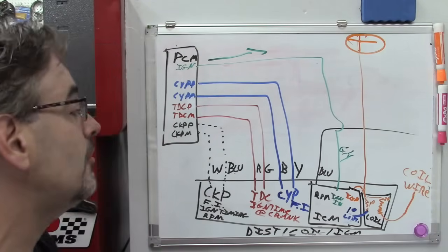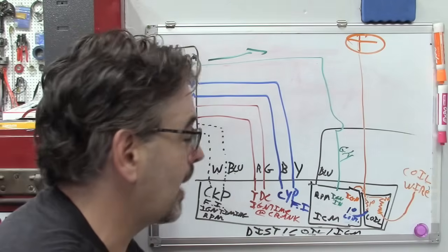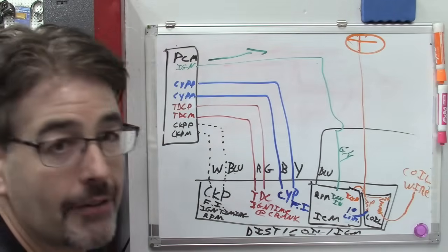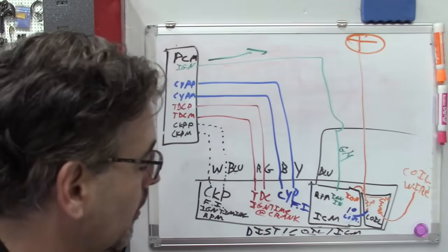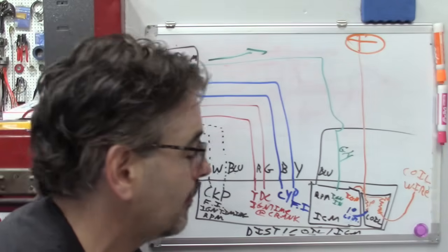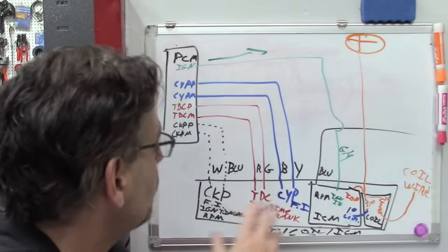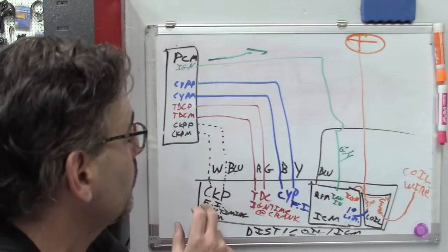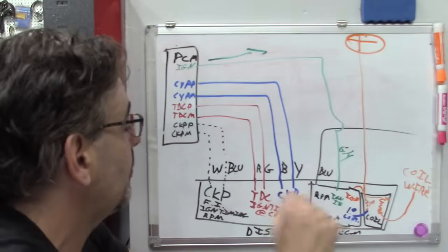So we've got all kinds of things we can do now. It's funny, now we have the exact opposite problem as before. Earlier, we really didn't have a direction to go on. Now I'm thinking, do I just want to go ahead and try to fire this coil on my own and rule out if the coil's the problem and it's more a control thing? Or do we want to test our controls and rule out any of those failing to send signal to the coil?